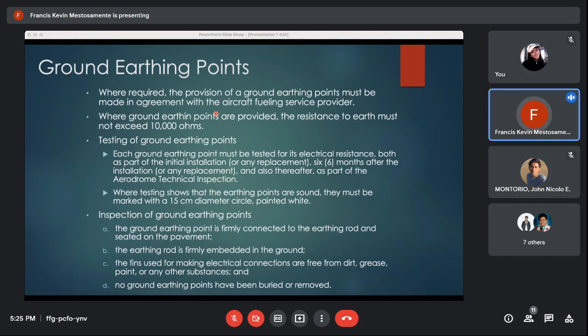Even yung mga maliliit na electrical charges, pumapasok yan sa ground points. Kasi, especially when nagre-refuel tayo, hindi naman kailangan na malakas yung electrical charges. A few spark could light up yung fuel. So, all electrical charges na hindi kailangan, dito yan pasok. Few numbers to consider here.